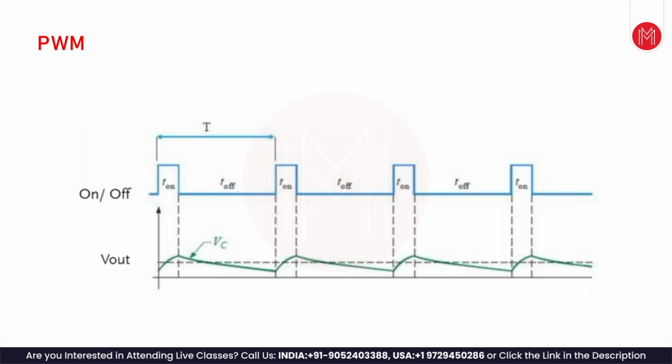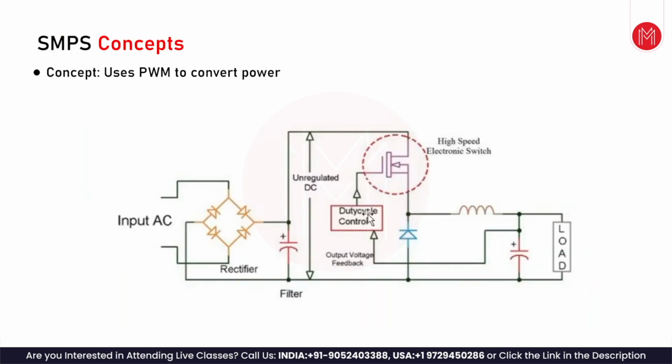Here there are no voltage drops and things like that. Whatever the voltage is there, the same energy is transferred to this capacitor at a lower voltage, because it charges linearly, and it will be maintained only at the voltage required by the duty cycle. So there is no drop or dissipation in any circuit element. It is simply transferred by the conversion process.